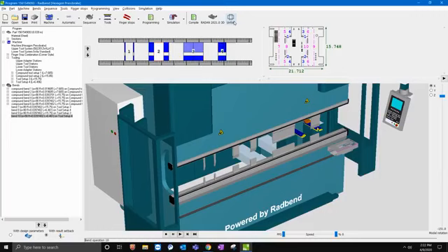Or you can simply hit unfold, and it'll create a DXF that you can put on another machine, right? Say you're running a water jet that just takes a DXF, so you just want to output it as a DXF and load that DXF in your water jet. So it'll actually save the DXF, right? So all that's good. We should be good to go.